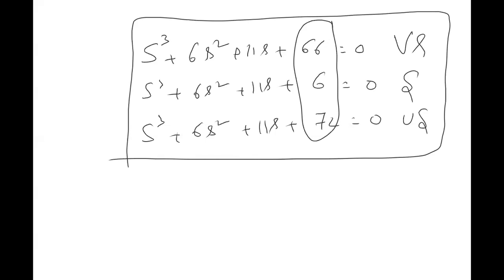See, even a small change. Maybe some of you might have one question. If one of the coefficients in the characteristic equation is negative, then the system is unstable. Have you heard this rule?